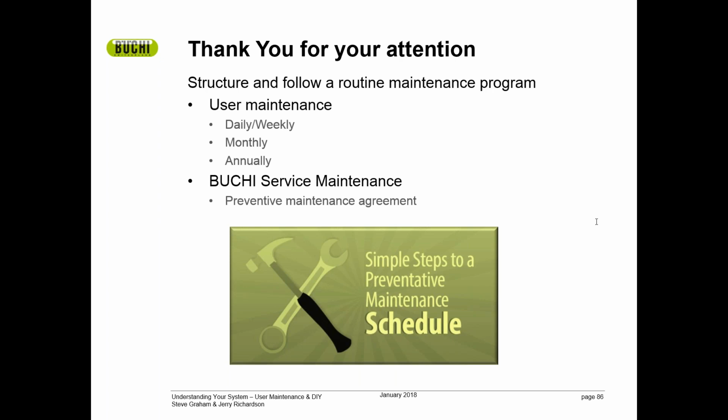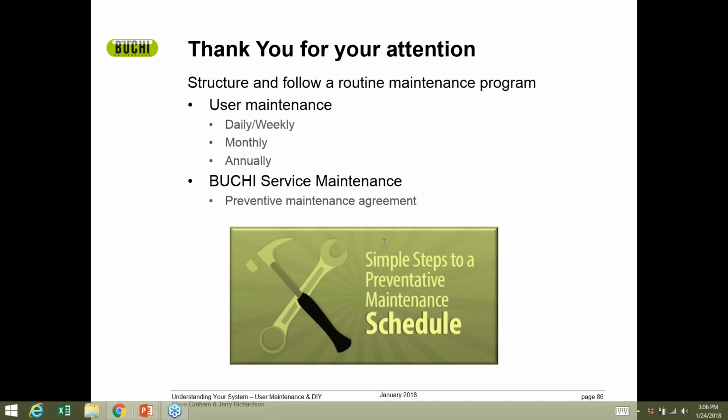If you receive the tube not present error, that is typically due to the sensor being out of alignment with the sample tube. So back on slide 30, we went over how to adjust that sample tube sensor so that you can remedy that error.